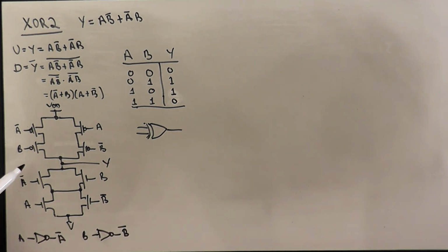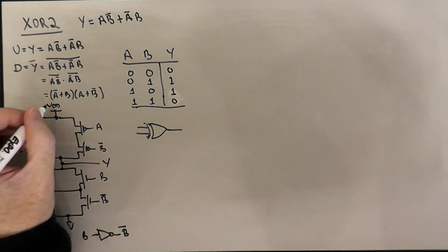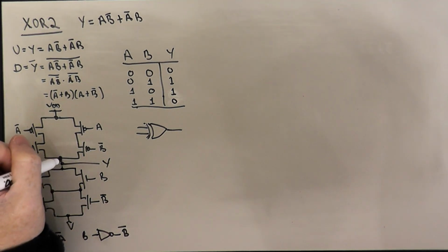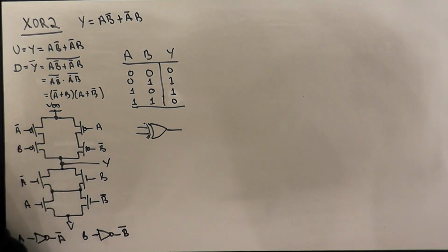And so this is a little more complicated gate. Here we have 8 transistors in the gate plus 4 transistors in the inverters to generate the complements of the input signals. And so the XOR gate is actually used quite a lot in generation of parity bits, and it also factors into things like adders, and it's just a generally useful kind of function. But you can see it's a little bit more complicated, and it's also not something that's nicely implementable because you need signal and complement all over the place. Okay, so I think that's going to be it for this one.